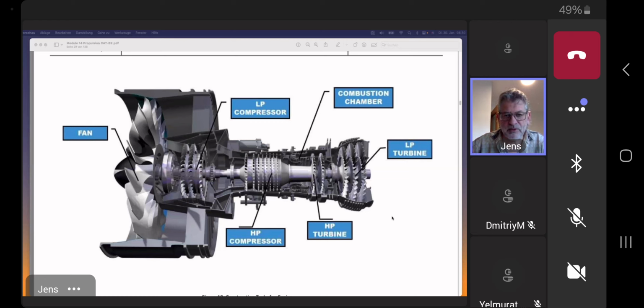And this makes turboprop engines very attractive for airlines, depending, of course, on the aircraft type and the flight profile they want, with maybe not so much range and not so high in altitude, and depending on the city and the amount of passengers too. So low weight, less fuel consumption, and since the gas turbine engines are not so, let's call it stressed, you have a longer period between the necessary overhaul, of course.